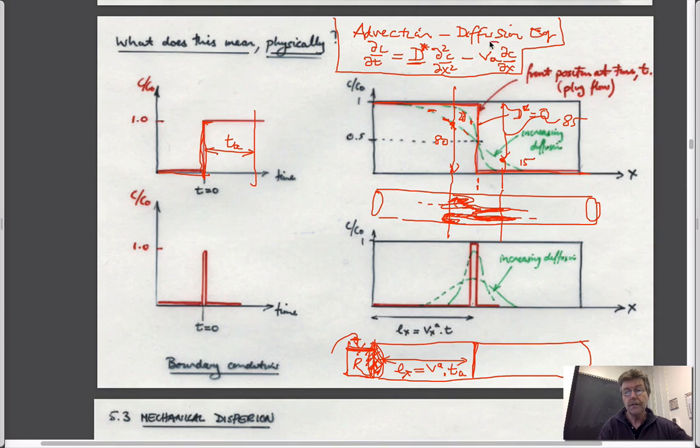This term here says something about the rate at which this front will arrive. And it's not a bad approximation for now for us to assume that this expression gives us it exactly. It isn't true, but for now, let's not worry about that. We'll disabuse you of that later. So that gives you the arrival, how quickly the beaker arrives downstream across the classroom. And the second part is the dispersion part, diffusion part. If this is 0, it'll be plug flow. If it's non-zero, it'll be progressively canted further and further over until it's very flat.